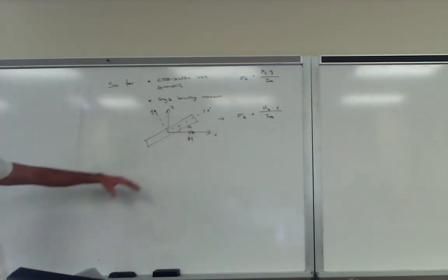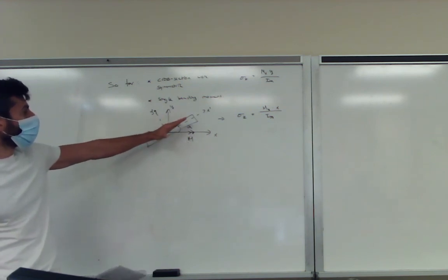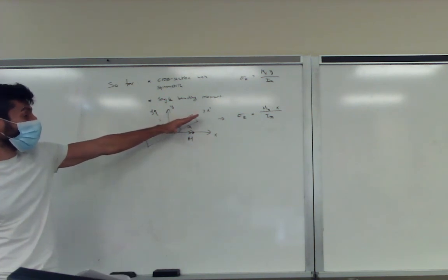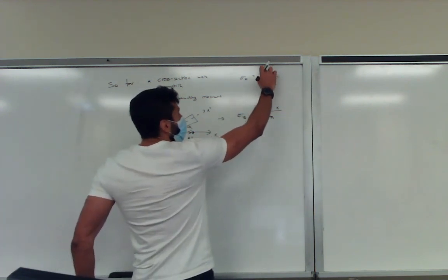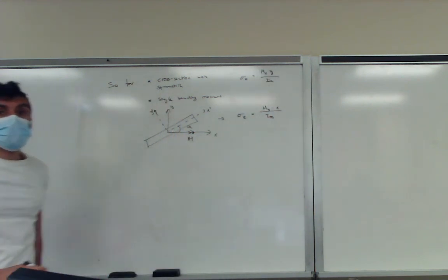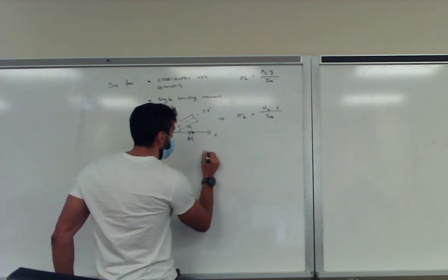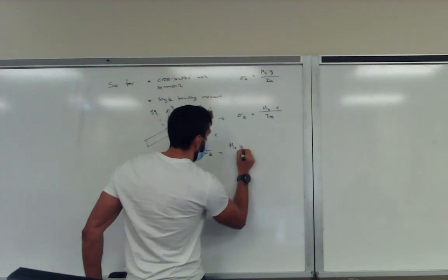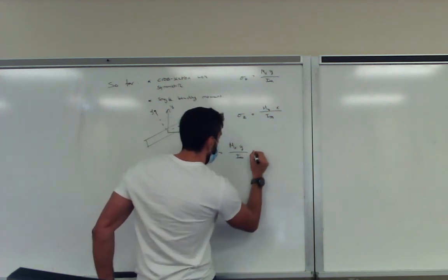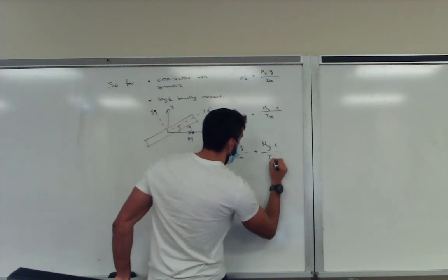So what we can do is we can decompose this moment, just like forces you can decompose, into a component in a new x-axis and a new y-axis. And now you basically have to deal with a component in x and a component in y. So if you want to have a combined section, what we can do is just superpose the two, they're independent of each other, and our new stress becomes Mx times y over Ixx, plus the moment around y multiplied by x over Iyy.